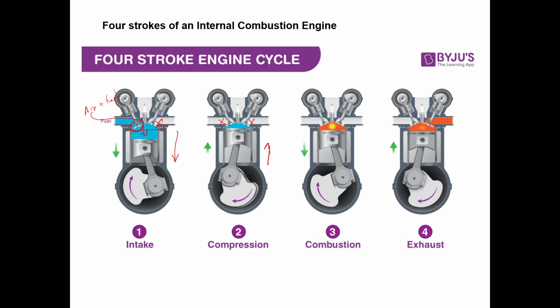Then after compression, when the piston moves to TDC, you ignite the spark plug. You supply a high voltage and ignite the mixture. Then you have the power stroke. After you ignite, the pressure increases and the temperature increases, therefore that drives the engine and pushes the piston downward. We call this the combustion stroke or the power stroke. At that time also both valves are closed. All the valves are closed.